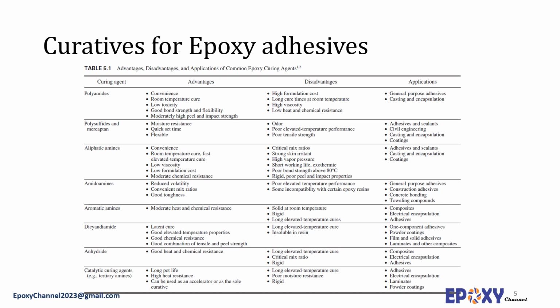Polyamide and polysulfide curing agents impart flexibility and are preferred in epoxy adhesive systems as they can distribute forces through the material matrix to reduce the stress concentrations. Anhydride and aromatic amines have also been employed, but to a limited degree. In hot cure adhesive formulations, they are often used. Advantages, disadvantages, and applications of different curing agents in epoxy systems have been presented in this table.